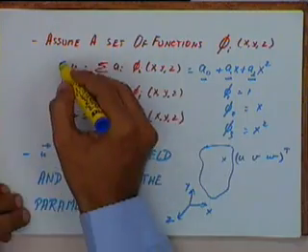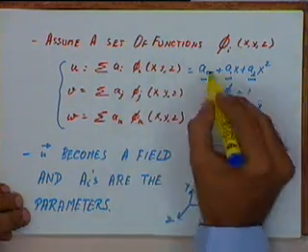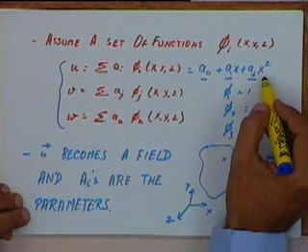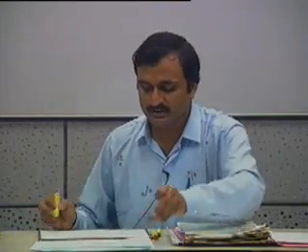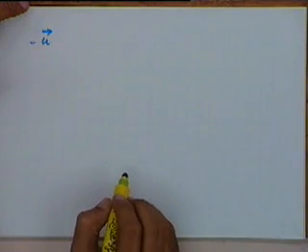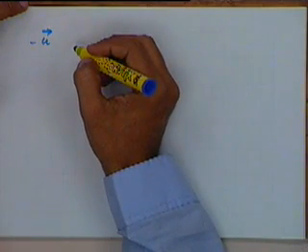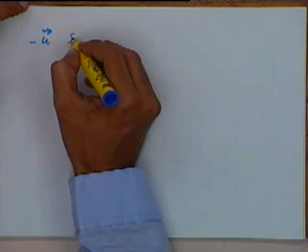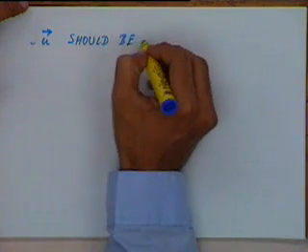So now I have got this deformation vector as a function of x, y, z, and it has some parameters a0, a1 and a2. The next thing that we do is that we say that this u bar or this vector u should satisfy the boundary conditions. Or we say that this should be kinematically admissible.